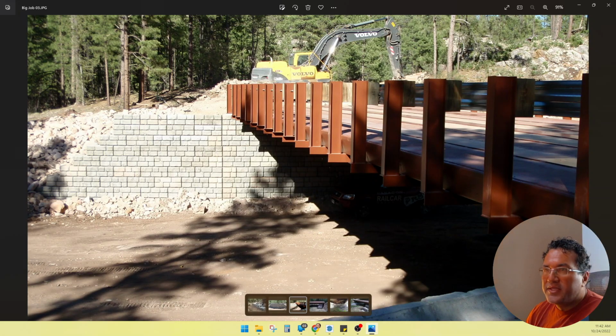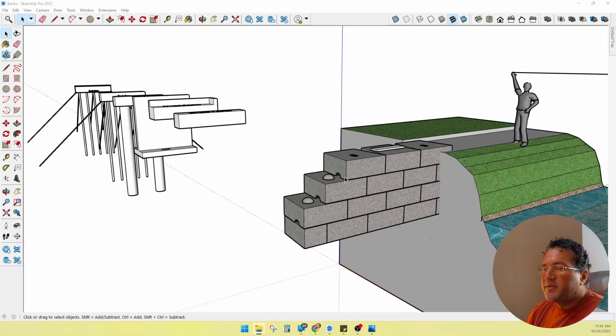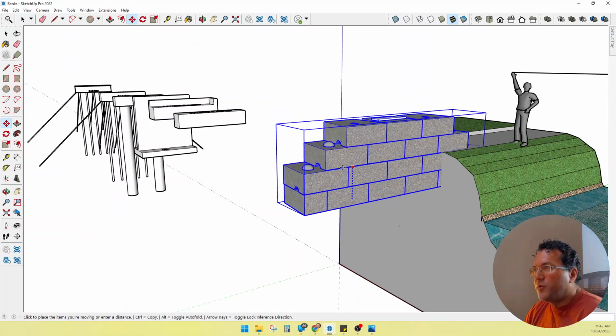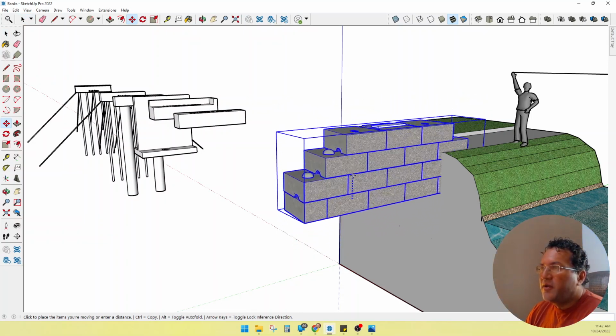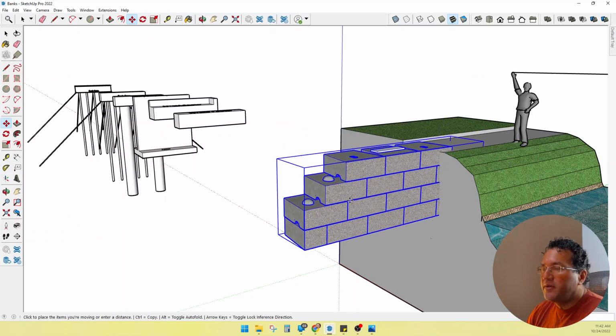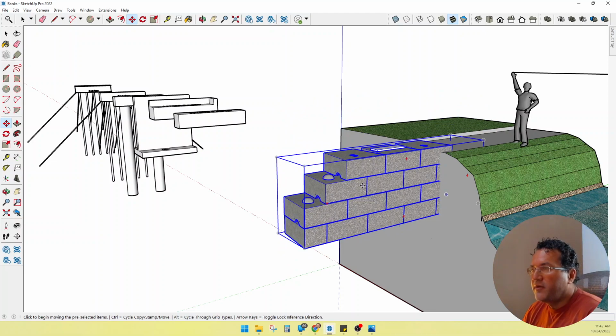So this adds a retaining wall to the side of it. That's a precast option. Set the bridge on top of there. With all these abutments, we can actually raise or lower the abutment depending on your soils. If we need to gain height in order to clear something, or lower it down, we can do that as well. As far as costs go, this is by far the least expensive, but it's not that much cheaper than the next option.